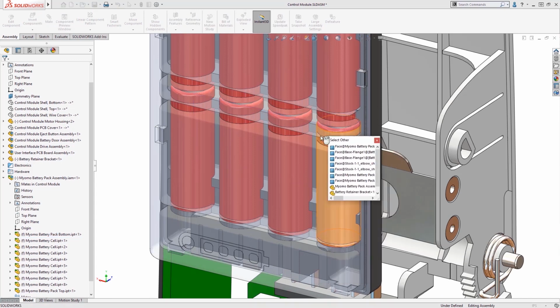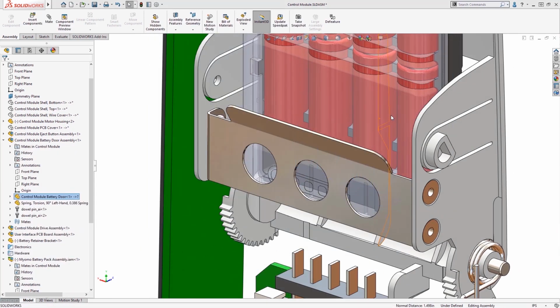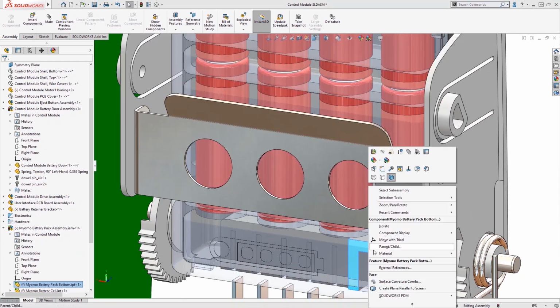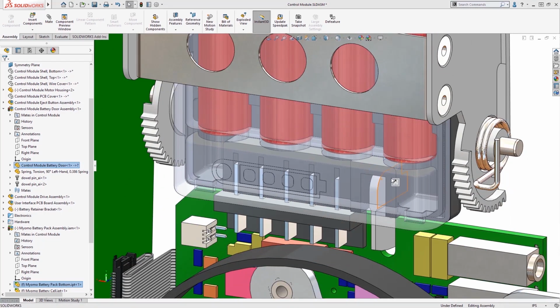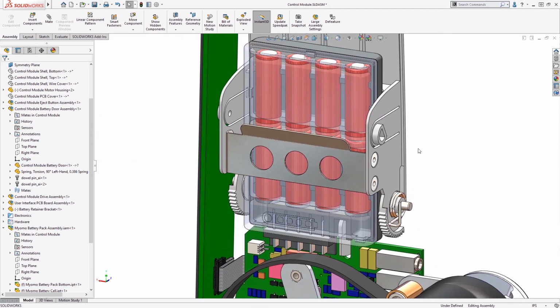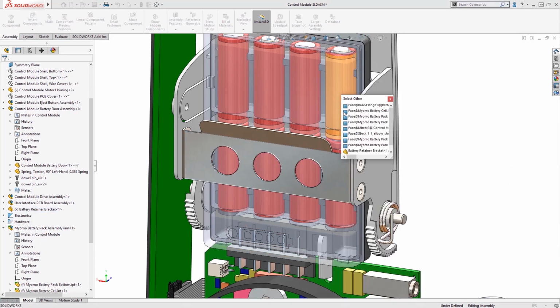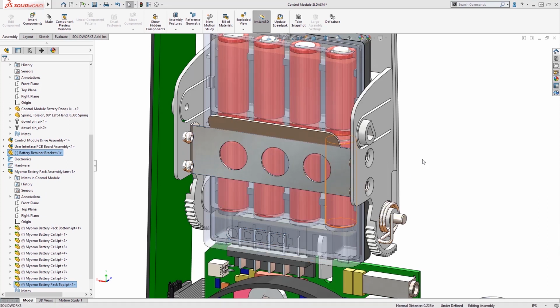We can use this assembly like any other SOLIDWORKS assembly, mating it into place using the provided reference planes. But because we have all of the 3D geometry, we can mate it to any surface of the components, just like you would with any other SOLIDWORKS file, allowing you to work the way you expect. We've also incorporated some design intent into this retaining bracket. Notice as we mate the back face of the bracket that the countersink holes and rivets along the side move as well. This is important as we've established some design intent here that ultimately references back to our Autodesk Inventor assembly.